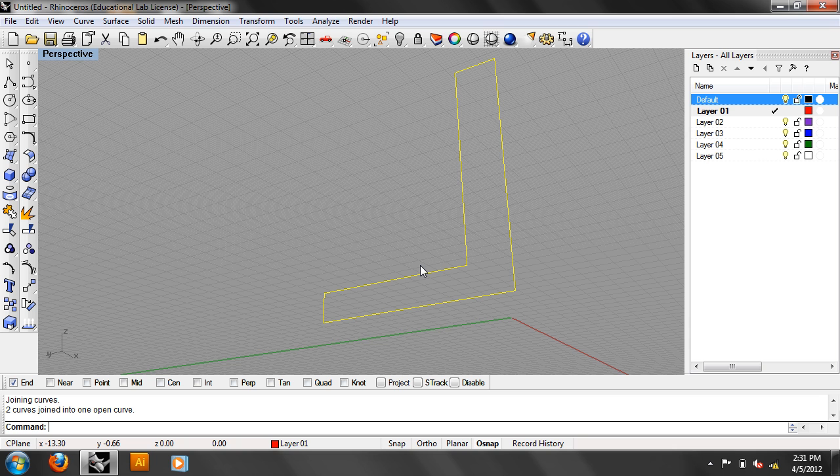So that's quicker. There's a command that lets you do duplicate border. That's the command, dupe border. And I'm recording this too. Okay, so you can do that. That's slightly less work, especially if it's really complicated. Like all you want are the intersections of the two things, and then you get a clean edge, and then you go in and do planar surface, and you get your clean piece.